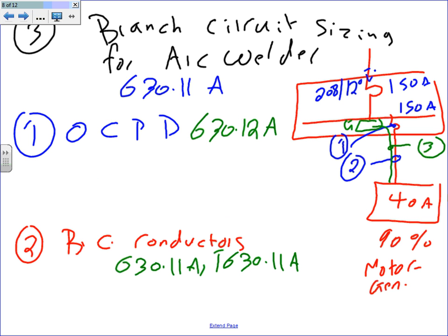Right in here, the overcurrent protection device. If you look at what we just said, it says 200%, which is 2 multiplied by the rated load amps. What's the rated load amps of this big fat boy? 40. No derating. 40, and that'll get you 80 amps. If it's not a standard size, you're supposed to go down, unless it doesn't hold, then you can go up. So the assumption is you go down. So here's 80 amps.